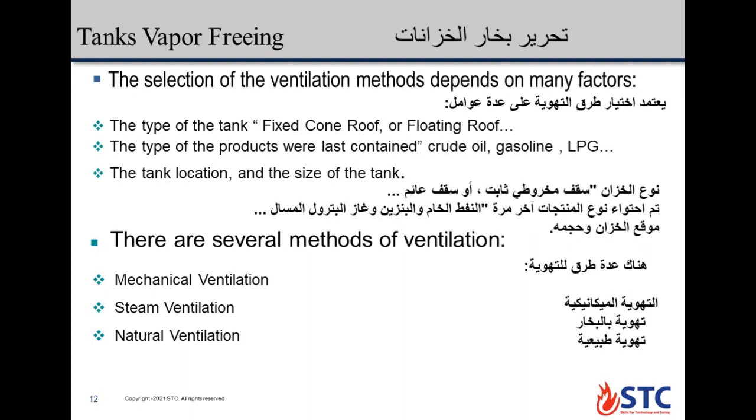So now 3 factors for the selection of the ventilation method. 1, the size and location of the tank, the type of the products last contained, crude oil, gasoline, LPG, and the type of the tank, fixed cone roof or floating roof.